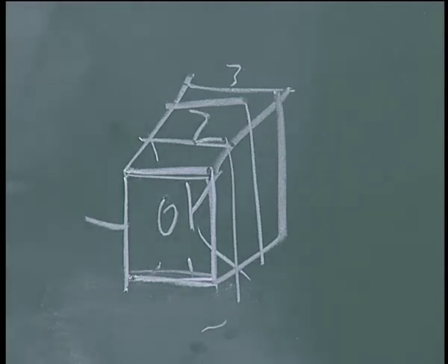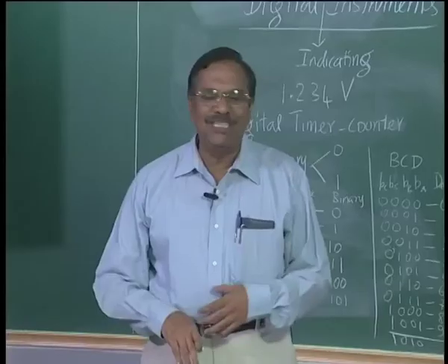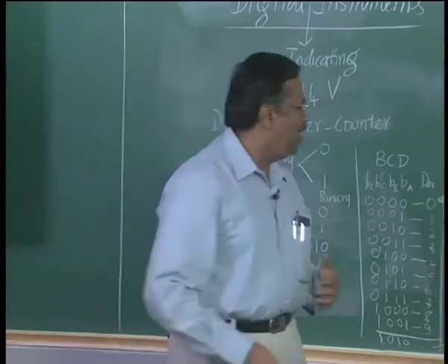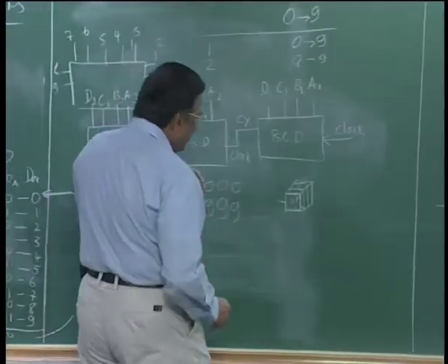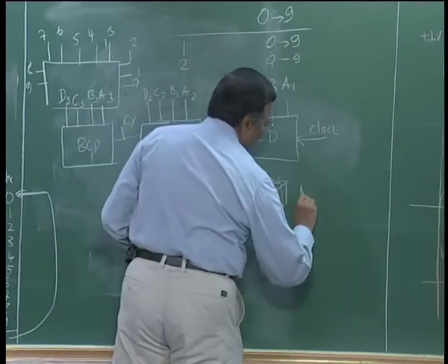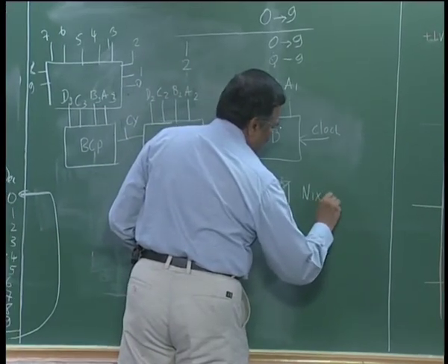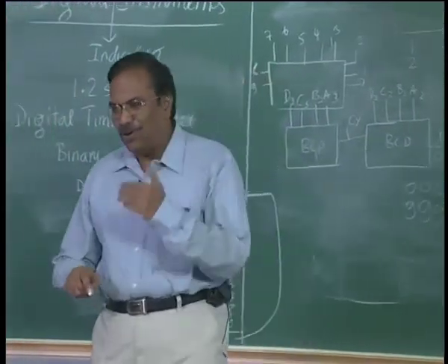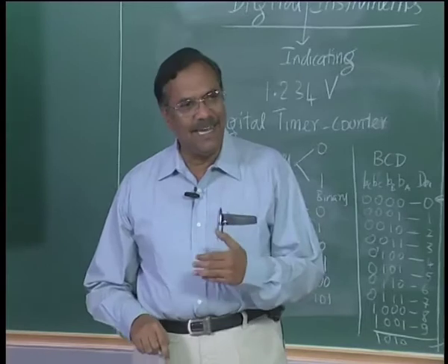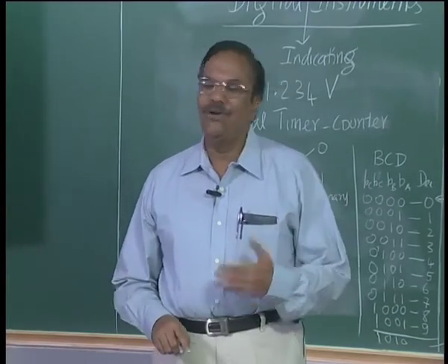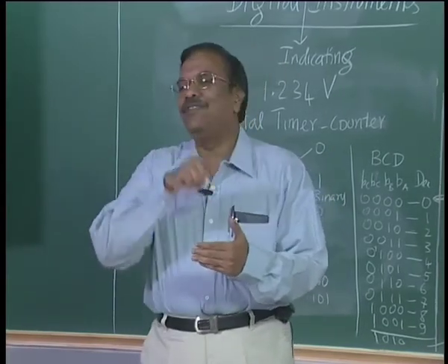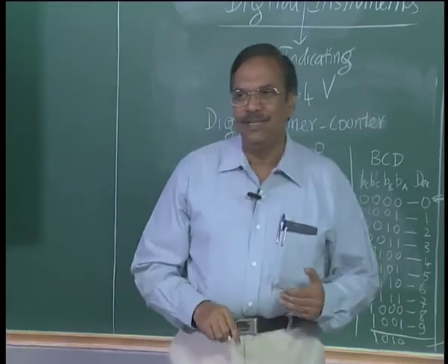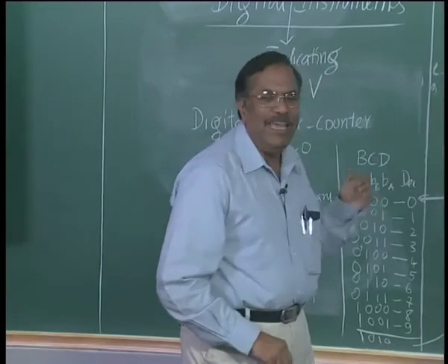If you want to do that, then you cannot put conventional bulbs, because one bulb will obstruct the other bulb. They came up with a nice display system called NIXIE or neon display system. These are just anodes which when energized will glow. The first anode will be shaped as 0, the second anode would be shaped as 1, 2 and so on. So if you look at it, the displays will go in and out.